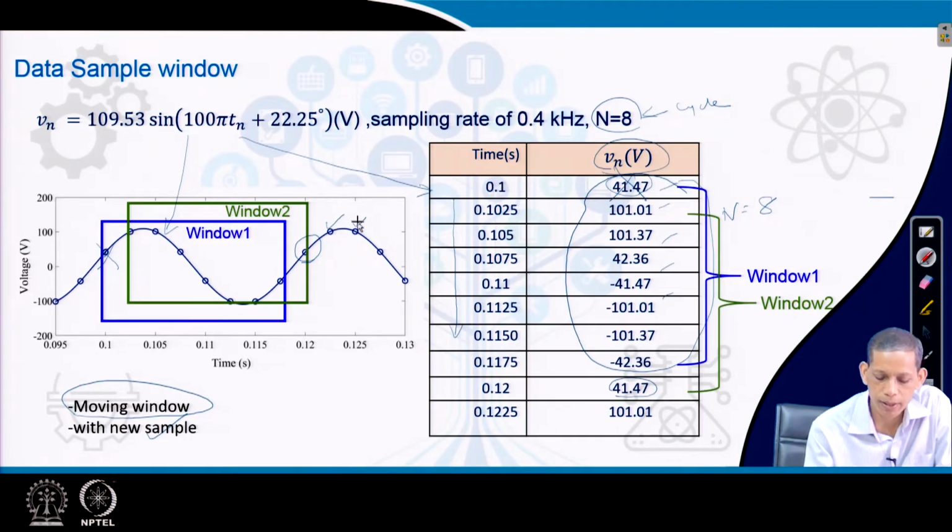One point again I am telling here: once a sample is acquired and the phasor is computed, the relay starts computing further things like currents, voltages, phasors, impedance and so on, and using its principle or method in this interval, the relay decides whether to trip or not trip.